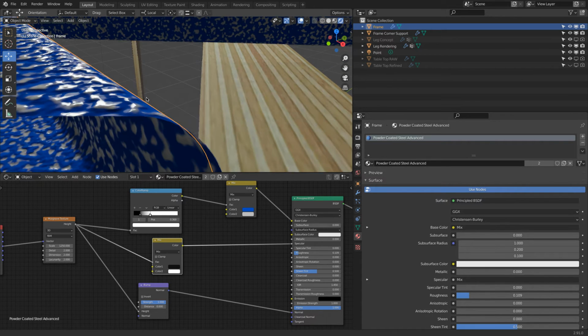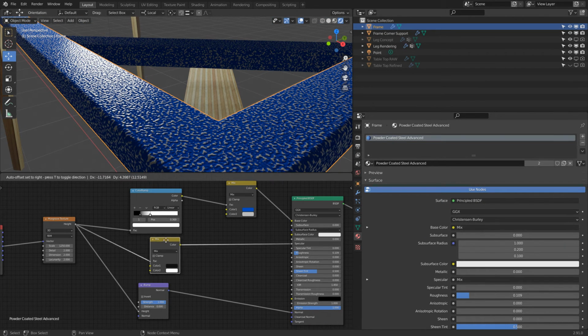Okay, very good. So this covers a little bit more of working with specularity and roughness and even adjusting what is reflective via a node. So either the color ramp or color mixer. The biggest difference between color ramp and color mixer, right now to explain this one more time. Here I have A to B. I have also A to B, but I can position them on a scale so I can clamp the values more. That's the main difference. Otherwise, the output is pretty much the same.